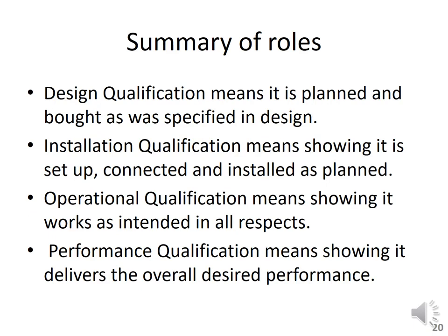Summary of the roles which are performed by all four phases. DQ, design qualification, means it is planned and bought as it was specified in the design. IQ, installation qualification, means showing it is set up, connected and installed as planned.